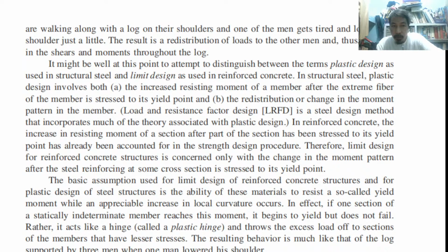Okay? It might be well at this point to attempt to distinguish between the terms plastic design as used in structural steel and limit design as used in reinforced concrete. Let us differentiate. In structural steel, plastic design involves an increased resisting moment of a member after the extreme fiber of the member is stressed to its yield point. Right? Take note of this. Okay? Take note of this.